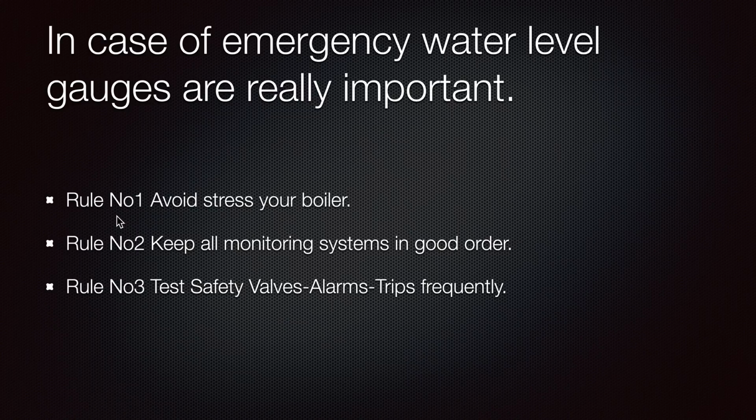Rule number 3 is to test the safety valves and the alarms and trips frequently. So this is your last barrier for your safety. And this is what will save you from the overpressure, from the overheat, and will give you a sign that you will be able to identify that something goes wrong.